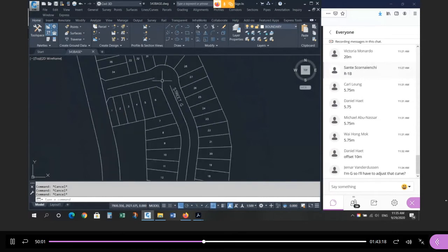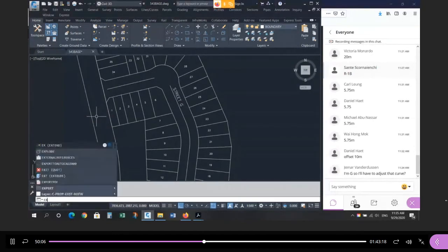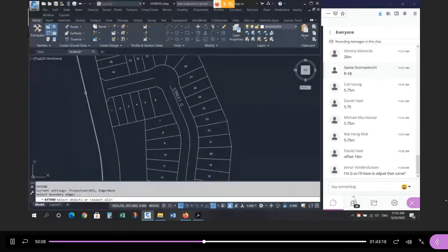Now, how do you deal with the center line in these unusual spots, right? How do you deal with it at the intersection? Well, we always take the center line across the street to the opposite right-of-way. So the center line of the pavement is here. We don't go to the middle of the road, we go to the opposite side. So that's where the alignment starts. So that's how you deal with the intersection.